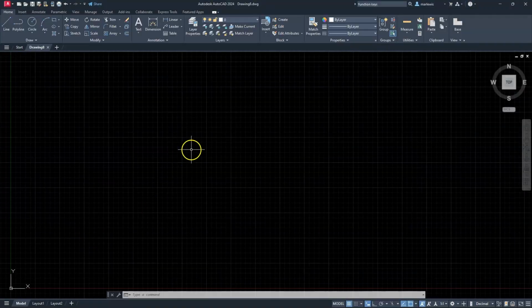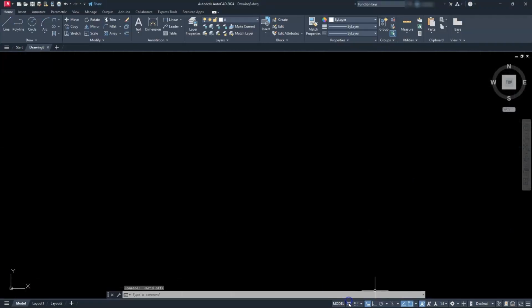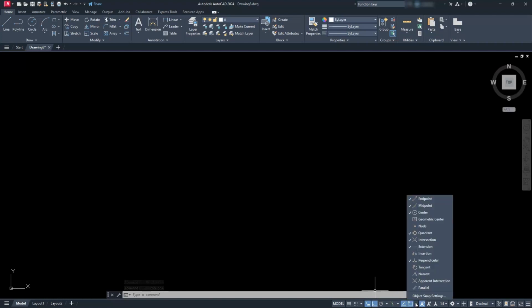Alright, let's go ahead and do our normal housekeeping that we normally do. Let's go ahead and turn the grid off. And we're going to go ahead and put the ortho on. We're going to make sure that we have our running OSNAP set. And we have all of those set.